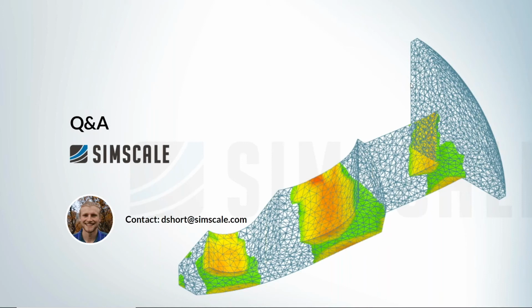Yeah, very good question. A lot of these fasteners will be designed so that they can withstand some levels of plastic deformation, but in this case, I would really say that was far too much stress, over and beyond the ultimate strength in large regions as well. So that's a big red flag saying this is likely going to fail on the first insert-extract type operation.